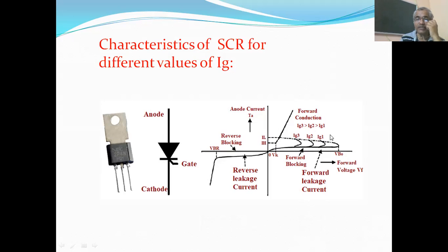One should remember that once the SCR is turned on by applying some gate voltage, the gate loses its control. The gate voltage loses its control means that even though you turn off the gate voltage, the device will remain turned on.